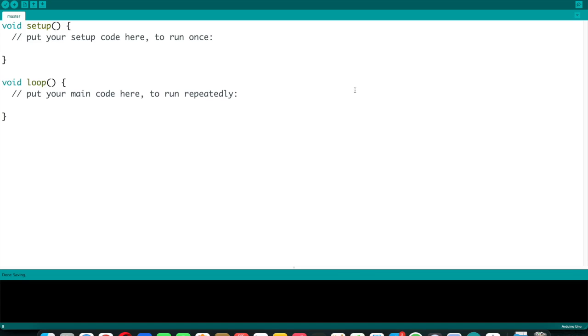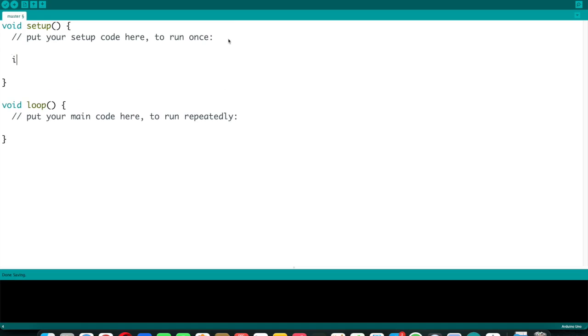However, you can also use Arduino C. For example, if I want to set up the direction of pins in Arduino C, we use pinMode, if you remember, or actually if you may not remember, but this is Arduino C. I could say pinMode, pin number 13, and I want it as an output. So pin number 13 is now an output. And pin number 13, this number is the number written on the Arduino board.